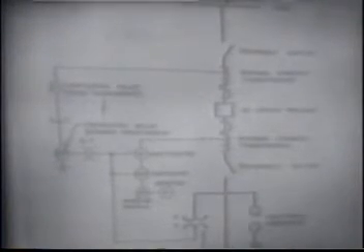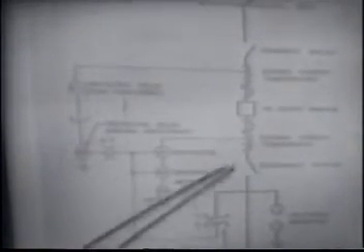It would reduce then the current flowing in this secondary to 5 amperes, which makes it reasonable then to carry this current into the control building, onto control boards with which people will be working, and on which we would mount then the protective equipment or the metering equipment. This gives us then a quantity that we can easily handle. If we were to try and use the full 1200 amperes, this would increase the size and complexity of all of these devices.